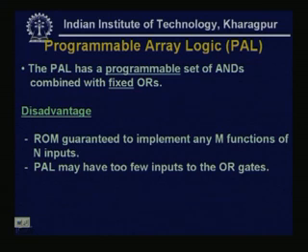And for M outputs, M different functions are there. For the M functions, any set of the 2 to the power n minterms, that means all possible minterms for n input variables, are available. So, PROM guarantees that, but a PAL may have too few inputs to the OR gates, because PAL has a programmable set of ANDs combined with fixed ORs.